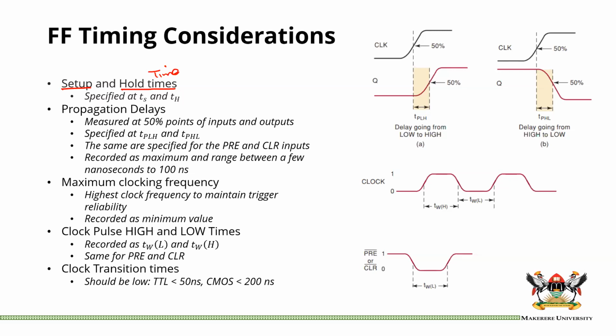We said that the clock transition and the inputs should not be happening at the same time. The hold time is the time after the active clock transition for which those inputs should remain in those states so that you enhance reliability. Then we have propagation delays.